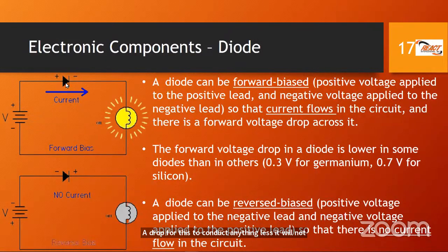If this diode is made from silicon, and by the way, note that it's silicon, not silicone. Silicone is that substance that you could use to seal and use for other things. You make different utensils out of silicone. But silicon is the element that we are talking about. We're in an amateur radio class, so we should strive to pronounce the words correctly. So silicon, not silicone. Silicon has a 0.7 volt threshold that needs to be overcome for current to flow. And that's actually an exam question, and we'll come to it in the next slide.